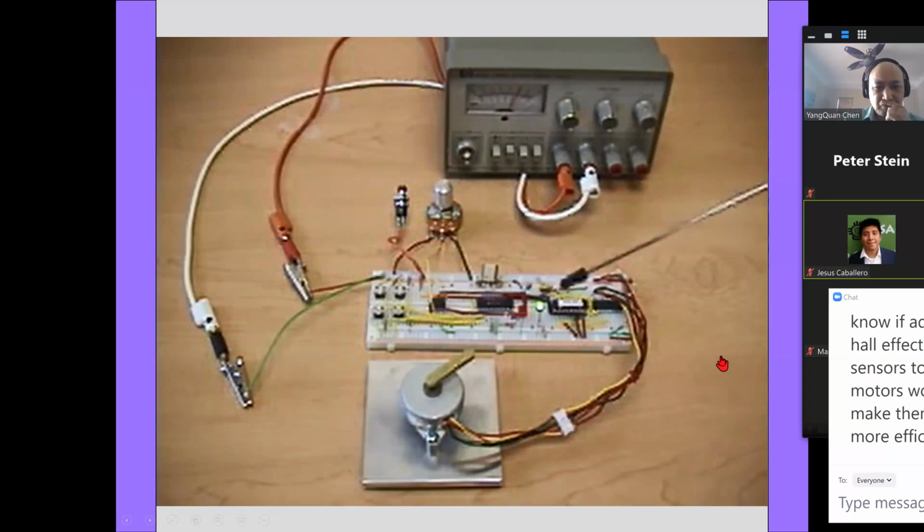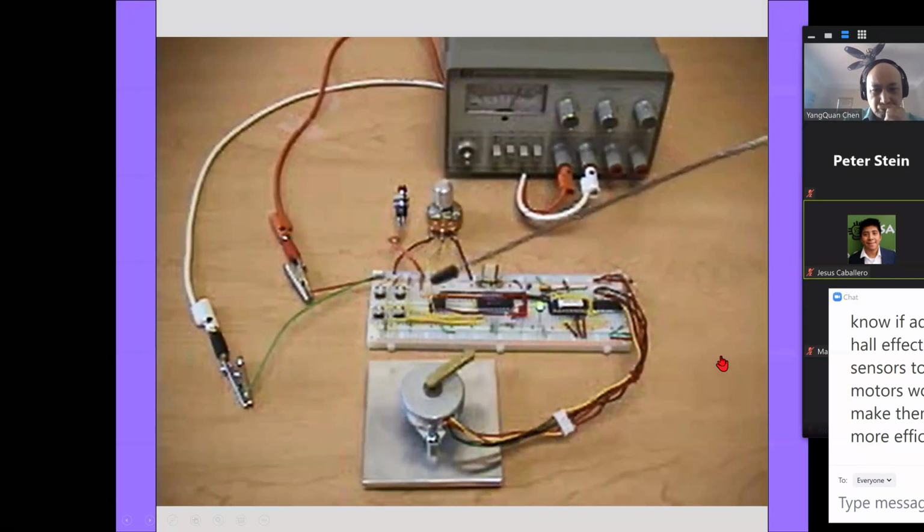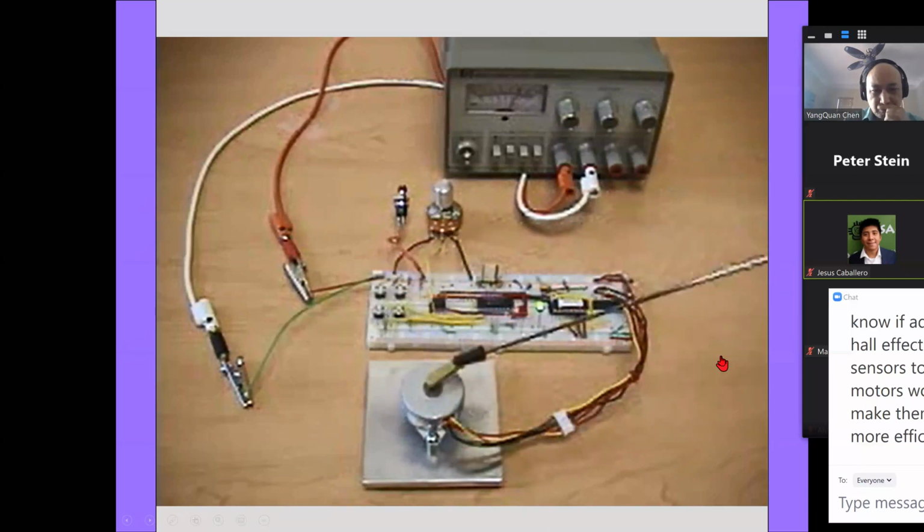We have 2 LEDs, one to indicate that power is applied, another one to indicate whether or not we're in speed control mode. We're using eLab's EDE1200 unipolar stepper driver and a chip with Darlington transistors. That's a ULN2003A. And those send pulses to the stepper motor in the proper sequence. Okay. The 4 position buttons position the motor at the current position, that's the first one, at the 45-degree position, the second one, at the 90-degree position, the third button, and at the 180-degree position, the fourth button.